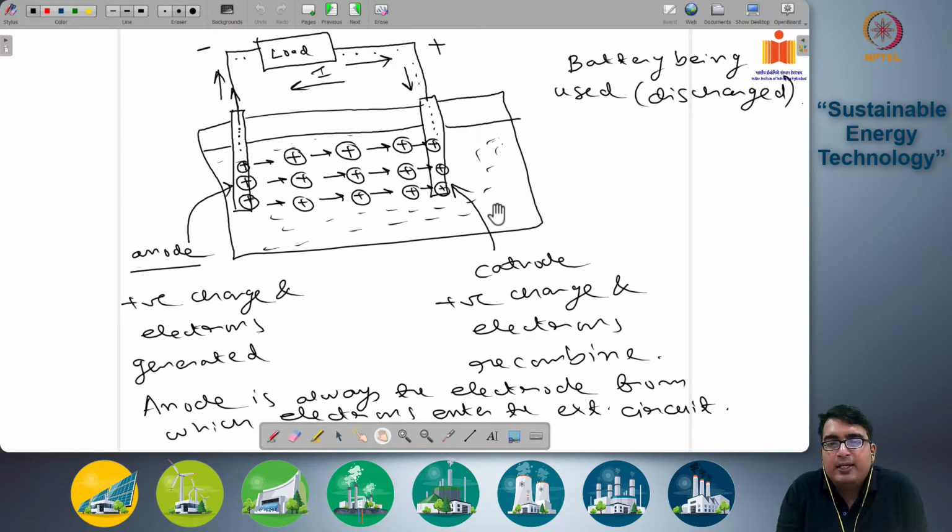So this figure, as we discussed in the previous class, shows what is happening inside an electrochemical cell when it is being discharged. And what we saw is in one side of the electrode, mainly the negative electrode associated with the negative terminal, you are getting a dissociation reaction which is consuming energy and creating electrons and ions. These electrons are flowing through the external circuit and are recombining in the positive electrode, which is the cathode for a discharge process, and this recombination is releasing energy.